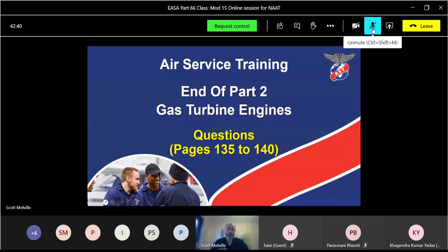So by changing, would it be the radius or would it be changing the length to make sure they're all in line? 50-50. So we change the radius or we change the length to move the position of the throttle lever. To make it position, we have to change the length. Yeah, that's right. Because you have set the range, how much it moves, but we need to select where that position is to make sure the lever is in line with the rest of them. Good.